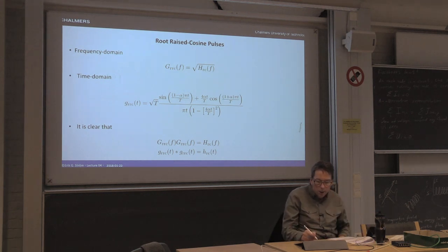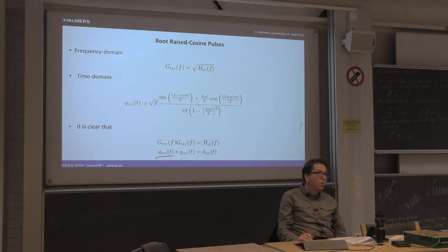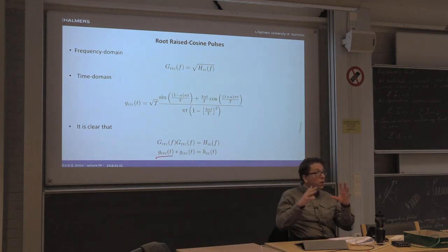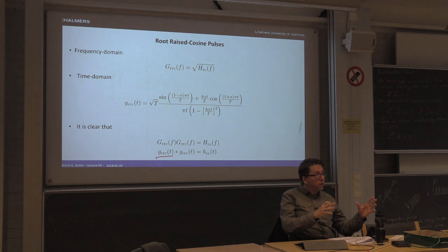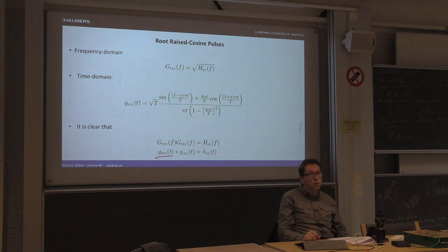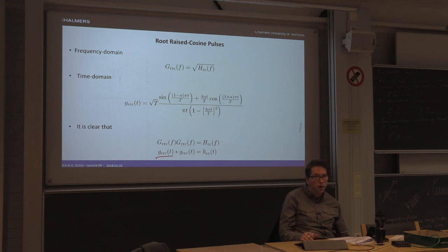So these are very commonly used as the basic pulse in pulse amplitude modulation. And then if the filter is matched to this pulse, then we don't have any intersymbol interference in our transmission. And then everyone is happy.